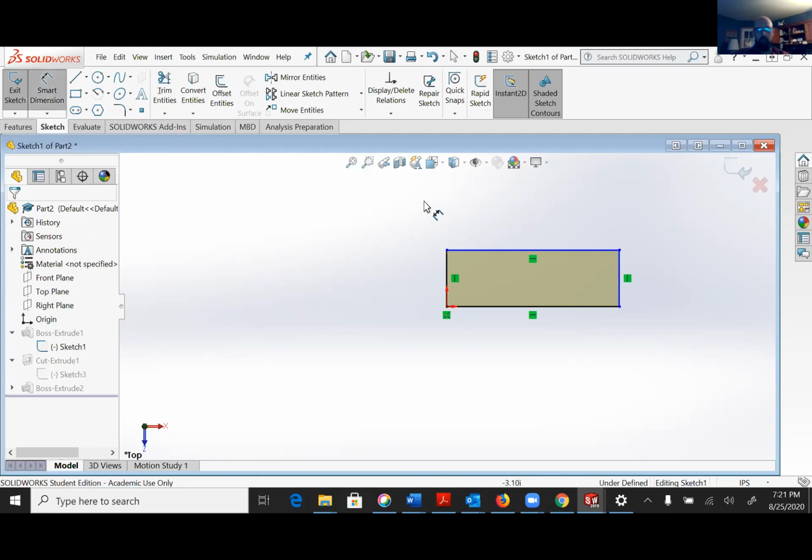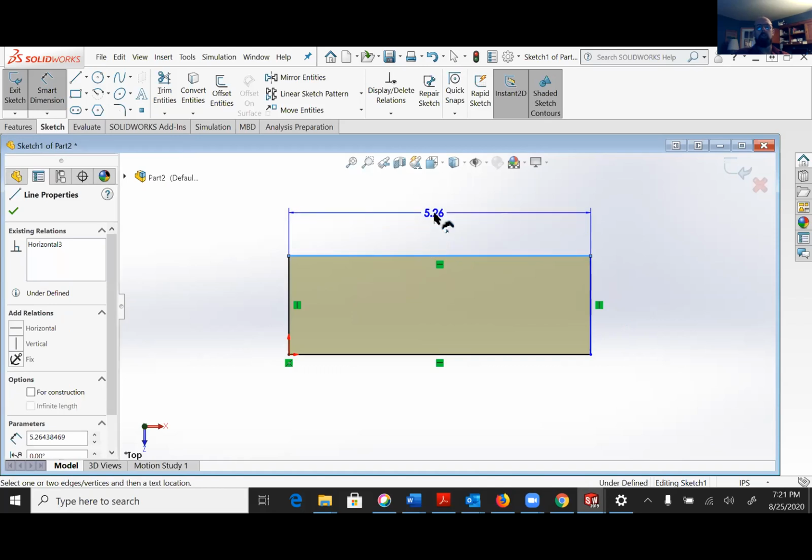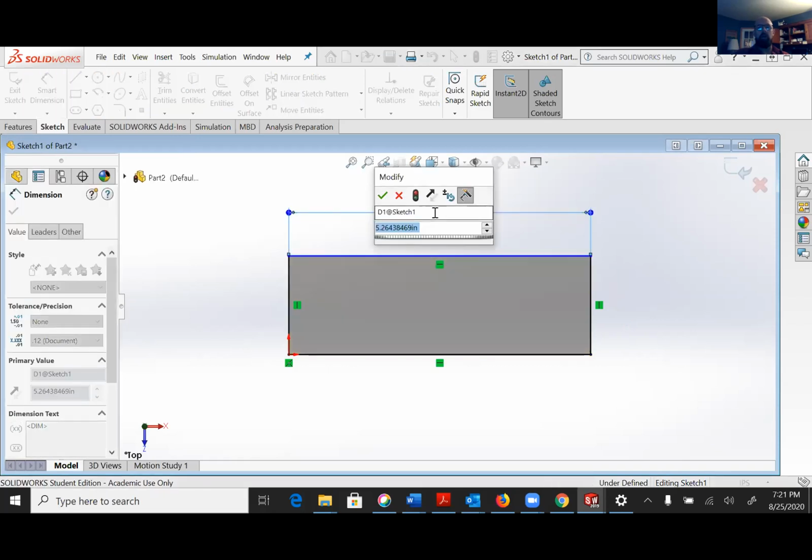Works beautifully, but you have to understand the few basics. And the basic is, I want to dimension this line here, which is between here and here. All I have to do is click on this line once and then drag. Again, you don't have to delete this. This is all ready to type a number in. 6, enter.